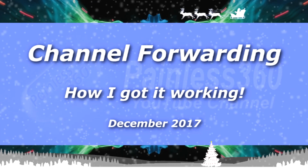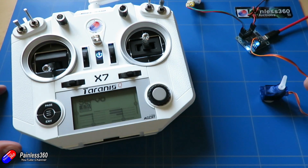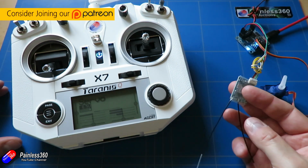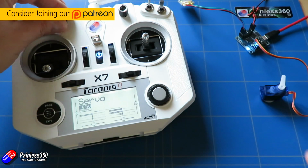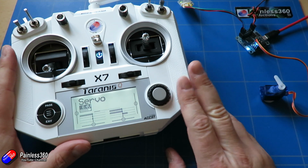In this video, hopefully I'm going to shed a little bit of light on how to do this. Now we have a servo connected into a flight controller and the receiver that we're actually using is just connected via PPM, but it could be S-bus, it could be I-bus, it could be anything. But what we can do is we can control this servo using one of the auxiliary channels on our radio.